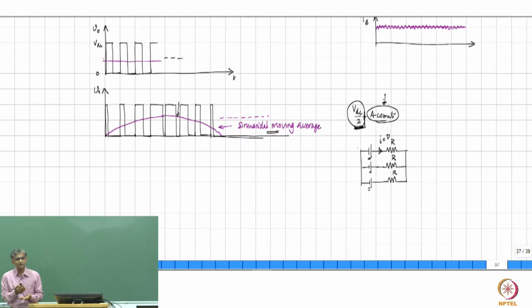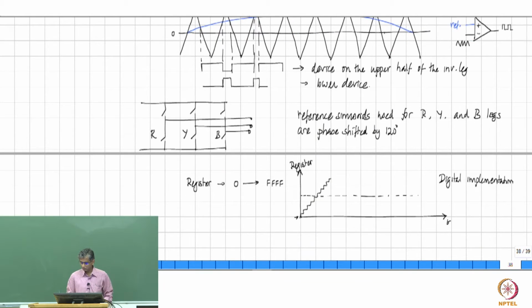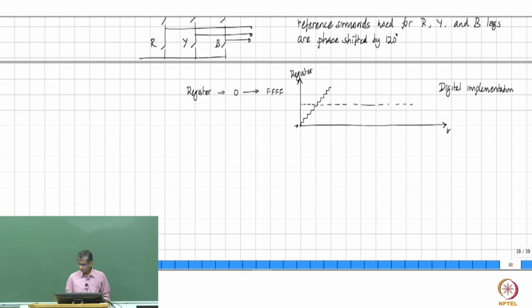It has been level shifted by DC, that's all, and that level shifting is harmless to the motor because you are level shifting all the phases. Right? Therefore, the motor doesn't respond, the motor responds to whatever is alternating, and therefore it works. Right?